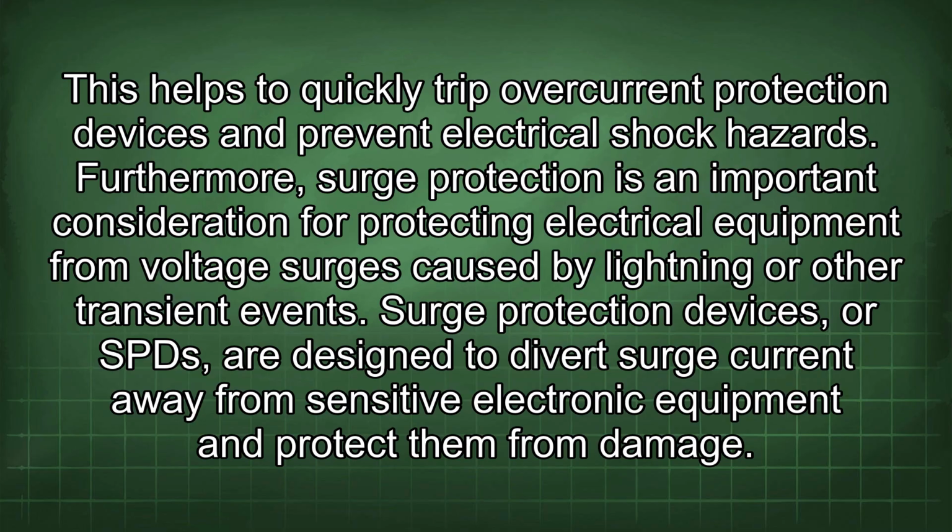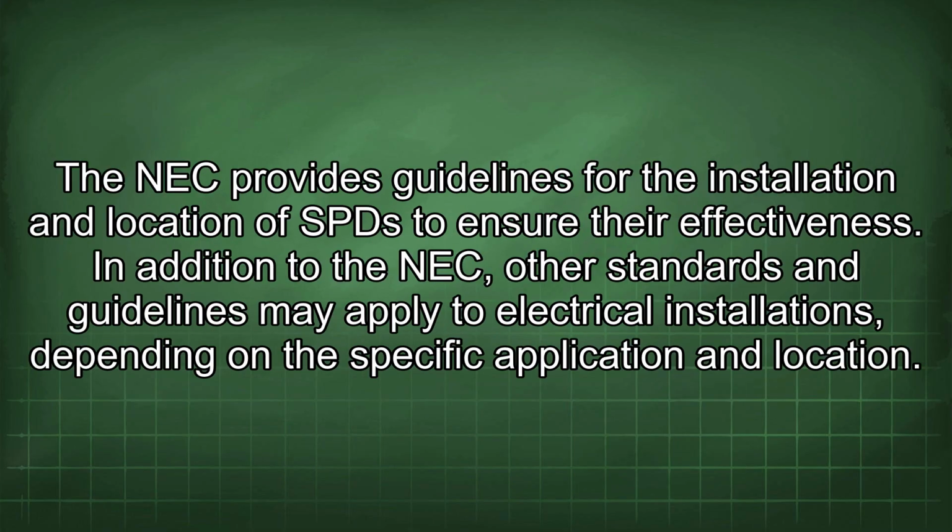Furthermore, surge protection is an important consideration for protecting electrical equipment from voltage surges caused by lightning or other transient events. Surge protection devices, or SPDs, are designed to divert surge current away from sensitive electronic equipment and protect them from damage. The NEC provides guidelines for the installation and location of SPDs to ensure their effectiveness.